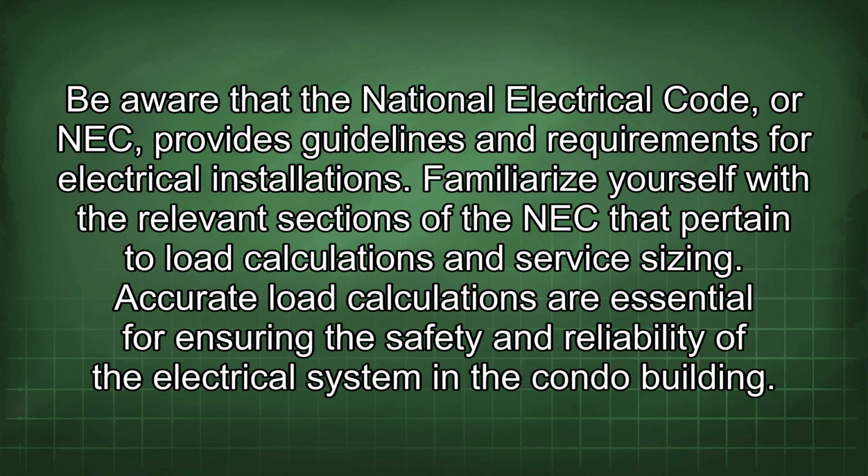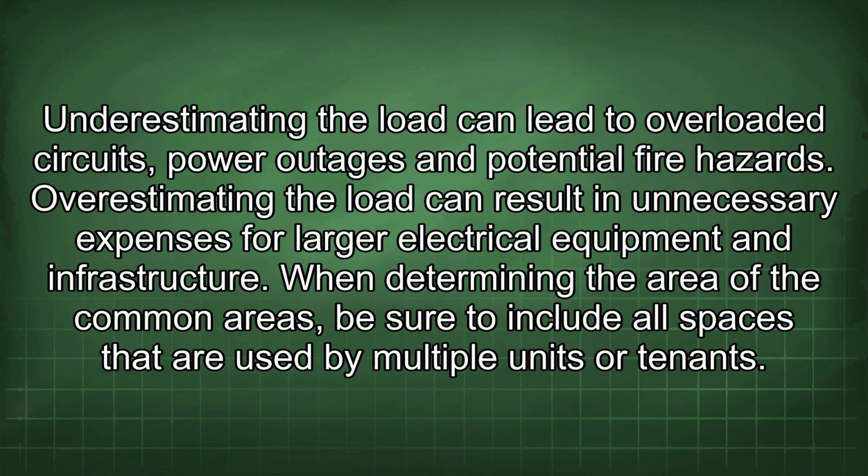Be aware that the National Electrical Code, or NEC, provides guidelines and requirements for electrical installations. Familiarize yourself with the relevant sections of the NEC that pertain to load calculations and service sizing. Accurate load calculations are essential for ensuring the safety and reliability of the electrical system in the condo building. Underestimating the load can lead to overloaded circuits, power outages, and potential fire hazards. Overestimating the load can result in unnecessary expenses for larger electrical equipment and infrastructure.